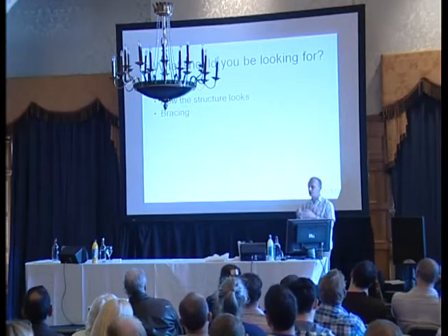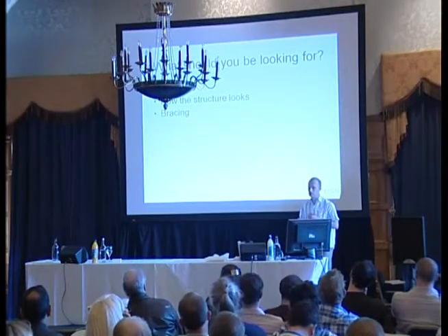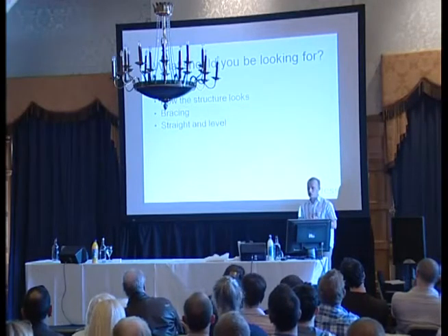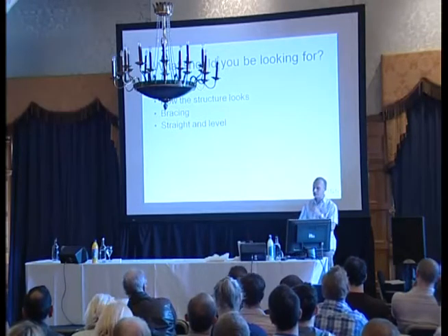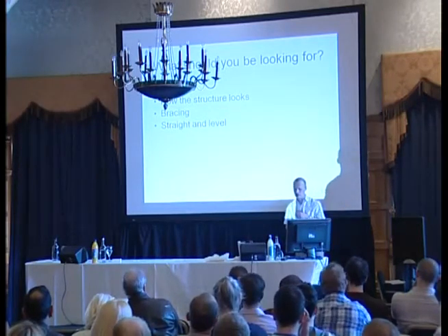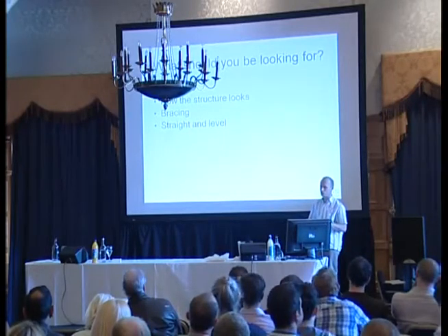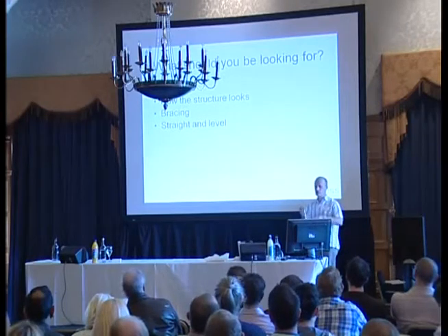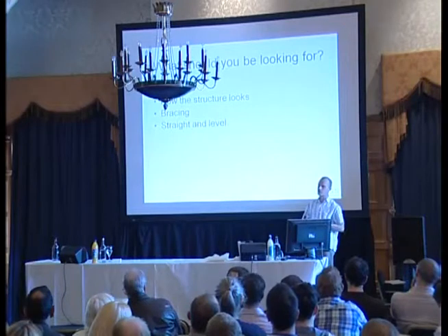You don't have to be an engineer to see that. You can pick it up yourself, yeah? A good pair of eyes is a very useful tool. Straight and level. When you get on your stage and it's up and down, up and down, up and down, you must start thinking, well, actually, we'd asked for a flat and level stage here, so what's gone wrong? You haven't accounted for the ground conditions underneath. You've got moving, bouncing pieces of decking. That means there's something wrong.